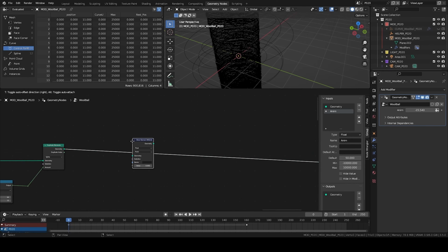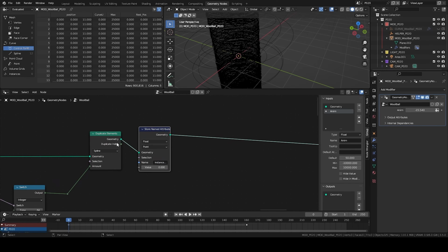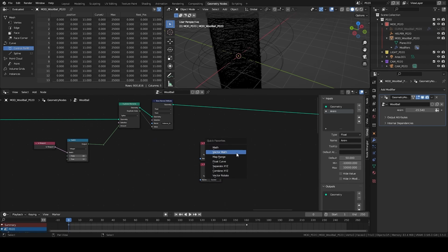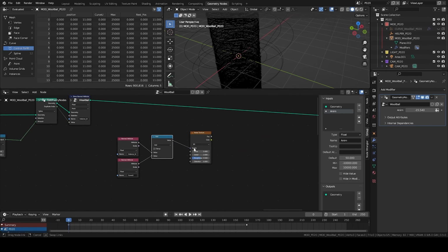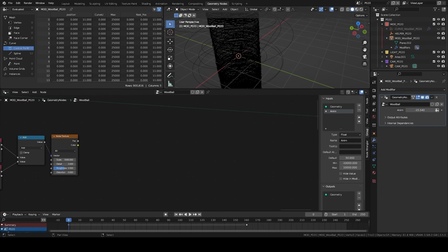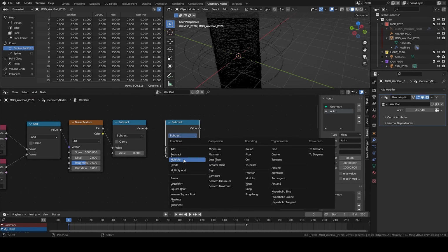I store the attribute. Still instance ID, which will be useful this time to create a shader. So we can keep it on point since it has just been promoted on the points. I create a named attribute node. There, I grab instance ID and I'm going to go grab curve view. I add them both up. That I plug into a noise, it's going to create a little bit more peculiar mapping coordinates for me. The noise is going to be very, very fine, at least 5000. A little bit of roughness. I'm doing the classic minus 0.5 manipulation with an amplitude behind, very low for once.